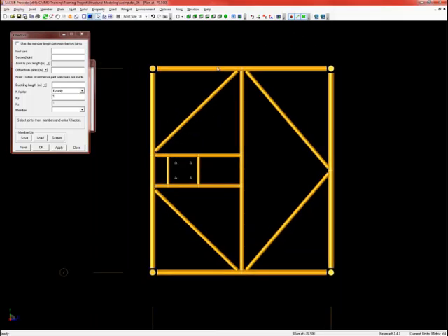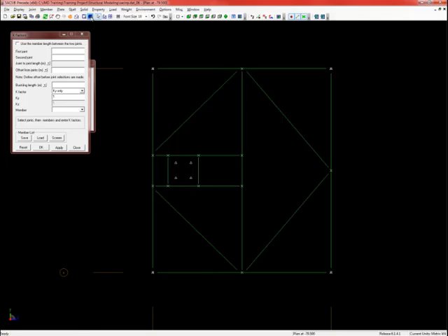Now let's turn the solid off, and if we hit this button over here, it gives you the arrows, so it shows you that the X is in this direction. X is always along the member, so that's something you can remember. The Y is already out and the Z would go up and down. So this is a way you can see we're going to be rotating about the Y.